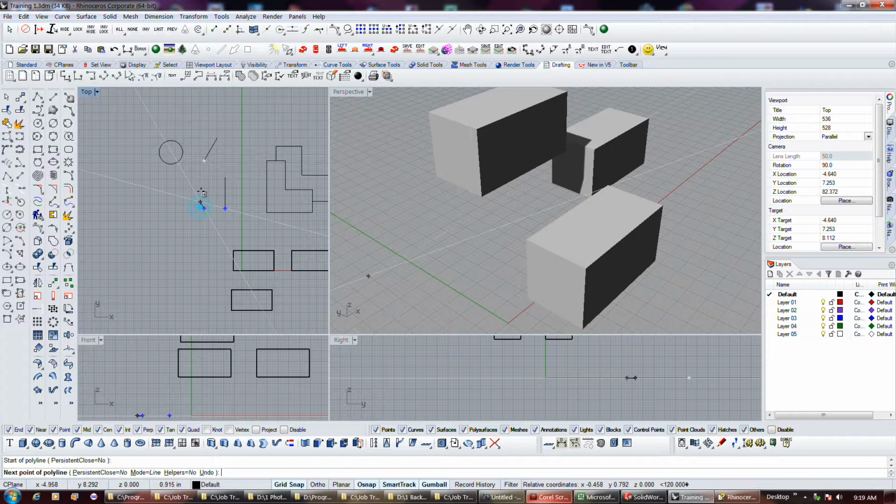But you can pre-select before you even start drawing a line. Is the whole point I'm making, and have an inference to different objects. This little video there shows them pre-selecting the center of the circle, but you really can't honestly do that. Not with so many snaps selected, so I'd have to have just like endpoint and center selected. But anyway, it's still pretty cool. And two, if you're drawing a line, if you just press Control at a given place, you can just place them out in free space to start your line too. So that's another option.